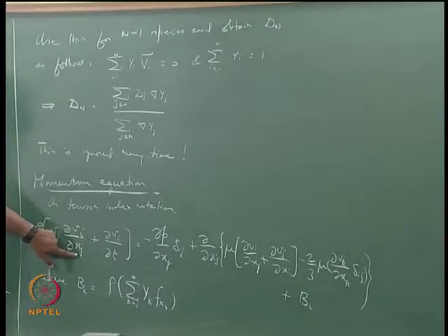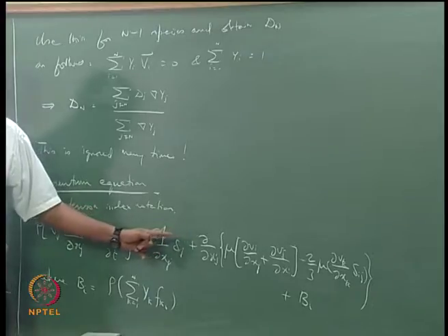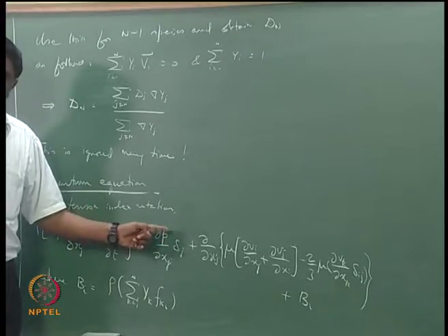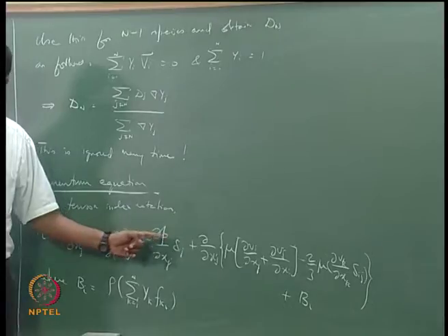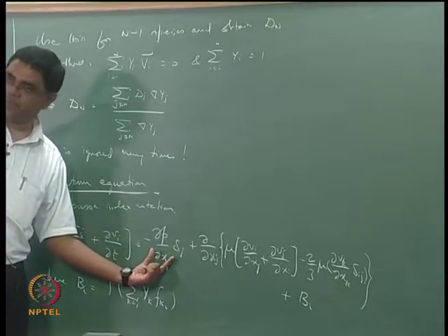Then I want to also point out that we have a summation over repeated indices. If you have Vj and Vj and Xj, then we have the sum over the repeated index. The remaining index will be i, which is the prevalent index in the entire equation. So this is for the ith component of a vector equation. The summation is in place over here as well, where delta ij is the Kronecker delta, which stands for a value of 1 when i is equal to j and 0 when i is not equal to j. Therefore this basically will give you a gradient of p.